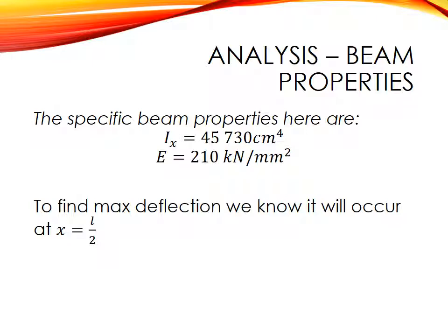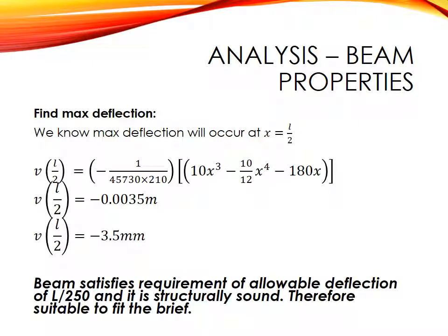As the beam is symmetrical, maximum deflection will occur at mid-span. These values are subbed into the expression for v, and a maximum deflection of 3.5 millimeters is calculated. This deflection is within the tolerated amount. Therefore, this universal beam can safely be used to support the load.